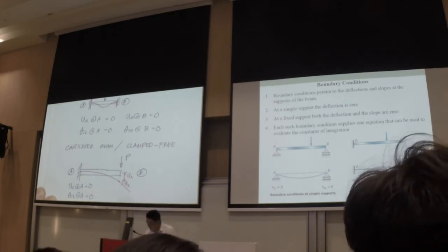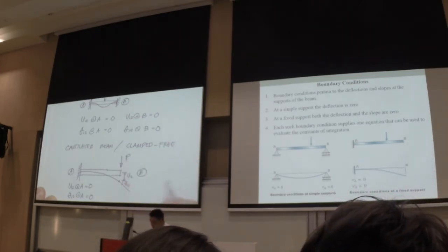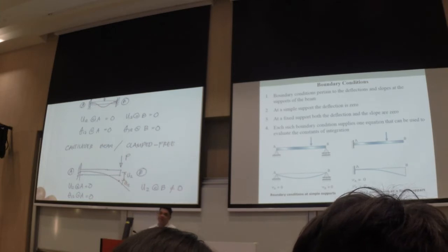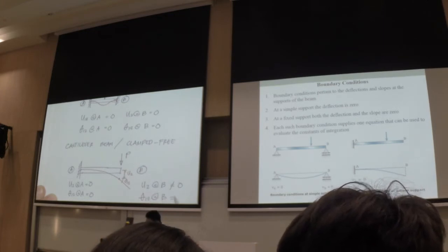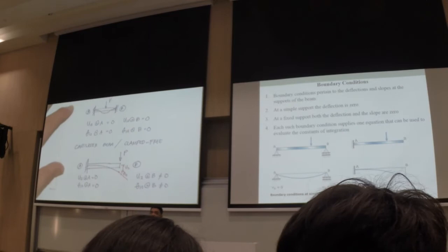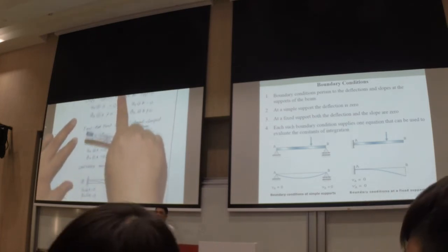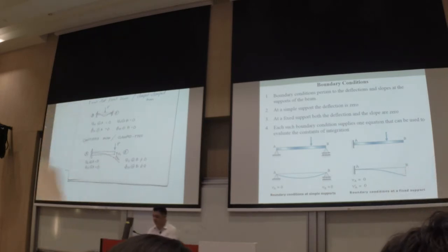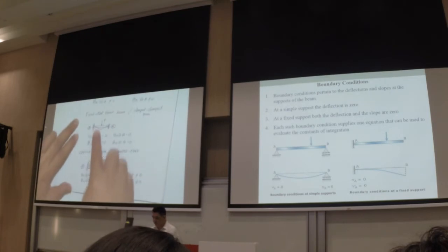Now, just looking at that, there will be a displacement, or what we call deflection specific for beam. Your deflection at B will be a value we don't know, so it's not 0. And definitely there will be a non-zero slope. Okay, so basically these are the things that we're going to learn. We have a simply supported beam, we have a fixed beam, and we have a cantilever beam. So pretty much just a combination. If there will be others, it's just a combination of the simply support, the fixed, and the free.